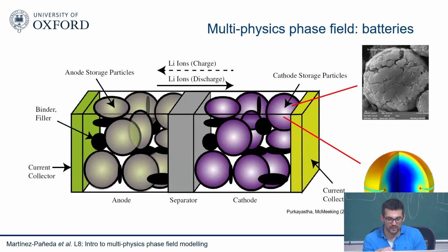And I should say, in hydrogen, we were the first to develop these phase field hydrogen technologies, but in lithium-ion batteries, there had been other groups that had already simulated phase field and lithium-ion electrode particle cracking. Both cathode and anode are electrodes, for those of you not familiar with this. So electrode particle cracking had already been simulated with lithium ions and phase field, but only for half a cycle because they didn't have fatigue, so they couldn't simulate the accumulation of damage that you get when you do cyclic loading.